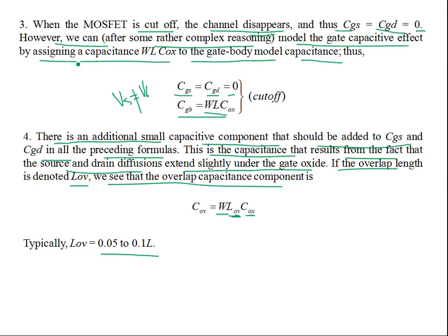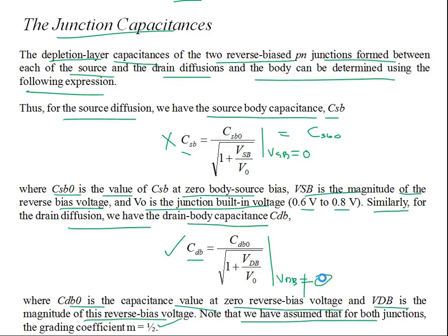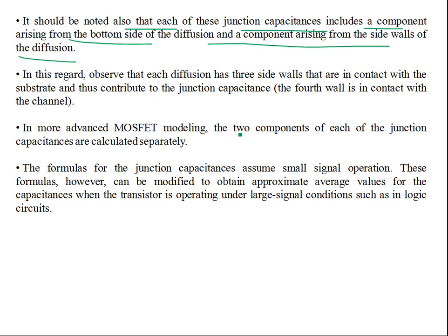It's all modeling work, but you have to understand that there are gate capacitances and diffusion capacitances. For example, in this figure, there are side walls as well. It's not this PN junction, but there's going to be a capacitive effect from the side walls, at both the drain and the source terminals. Also, you're going to have some effect from the channel side as well. So there are capacitances from the sides too. That's how the construction is.